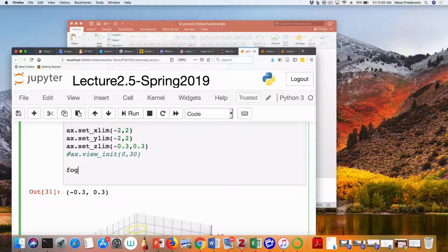So if I just want to save it, I'm going to say save fig. This type of function, save figure, or ability to save figure travels with my figure object. So I can do that in any figure that is created with PLT function. This is contour. And then extension. It's going to be smart enough to figure out standard extensions for figures: JPEG, TIFF, PNG. One of those will work.